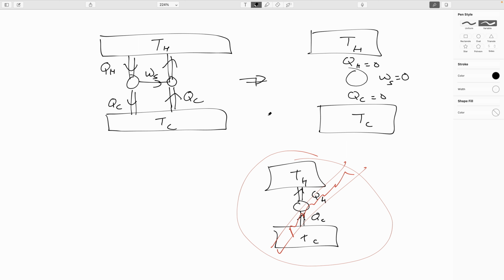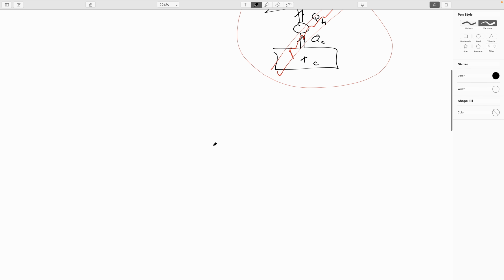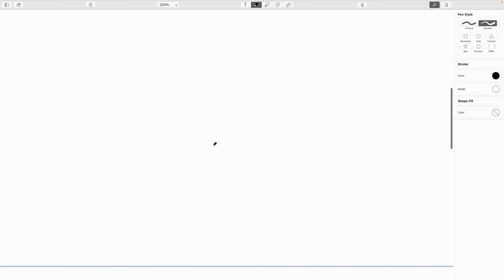Okay, so let's try to figure out, for such a perfectly reversible heat engine, in other words, one that I can actually draw the diagram for, what is the most efficient possible cycle that it could run? This turns out to be a thing called the Carnot cycle, spelled C-A-R-N-O-T. Now, to obtain it, I'm going to introduce a new diagram. We've seen PV diagrams before, so now we're going to have a TS diagram.